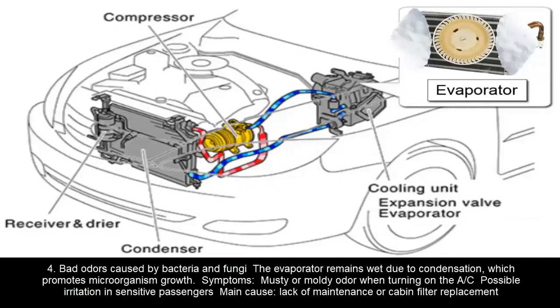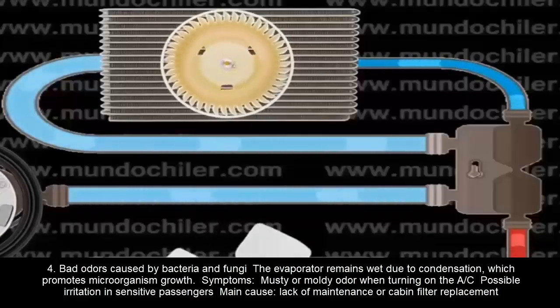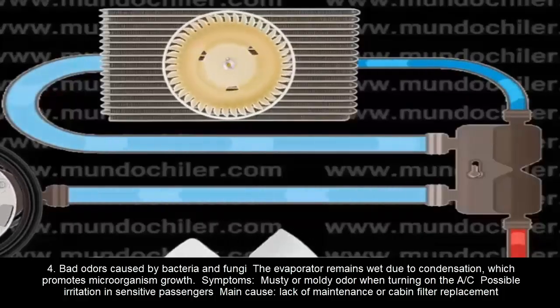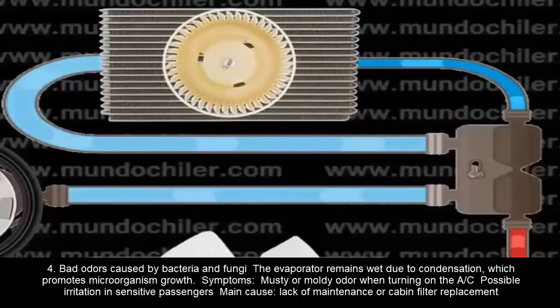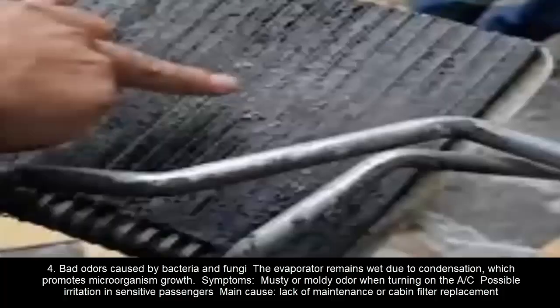4. Bad odors caused by bacteria and fungi. The evaporator remains wet due to condensation, which promotes microorganism growth. Symptoms: musty or moldy odor when turning on the AC, possible irritation in sensitive passengers. Main cause: lack of maintenance or cabin filter replacement.